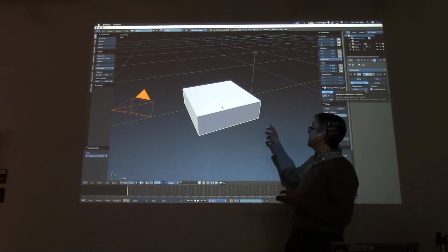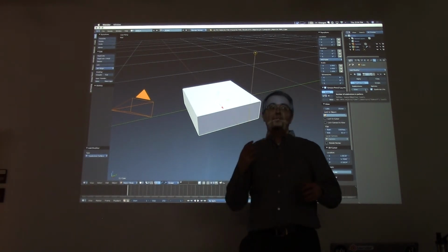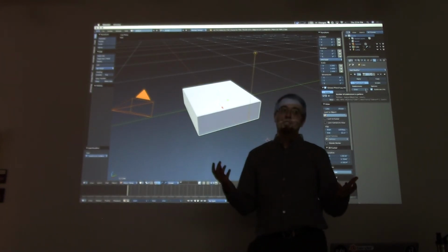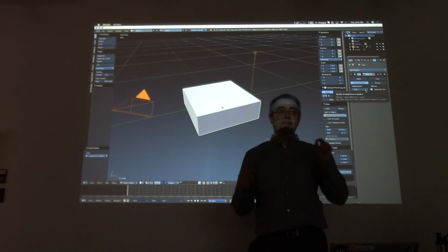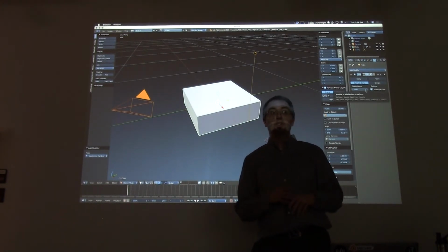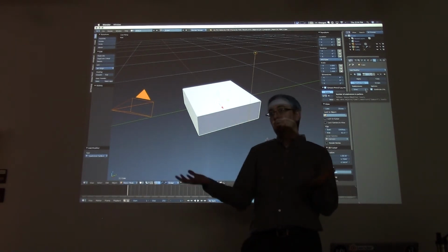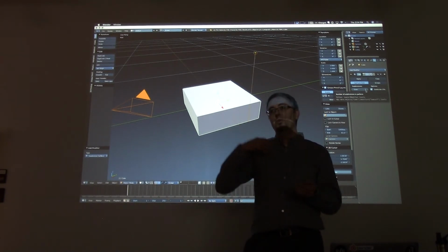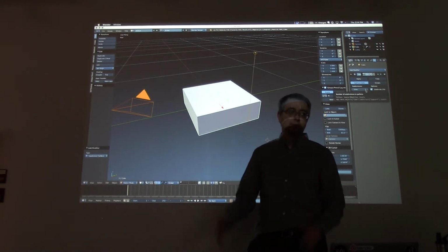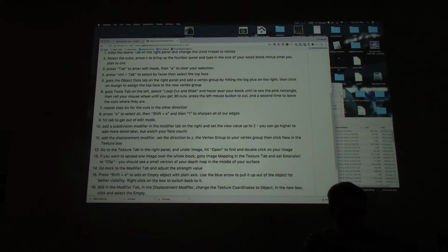This is one of those classic things where, when you're a 3D modeler and you want your object to have like 5 million faces and it looks awesome, but you can't actually model that way because your computer can't handle it, your view modifier is turned up to 2, and your render modifier is turned up to 5. Then it transforms the geometry to its smoothest ultra result when it renders, but it doesn't do it while you're modeling. That's the reason there are 2 different settings. Cool? All right, so we've done that setting, add subdivision modifier.